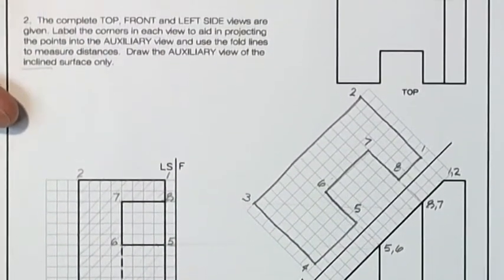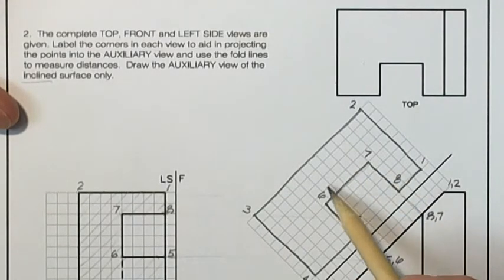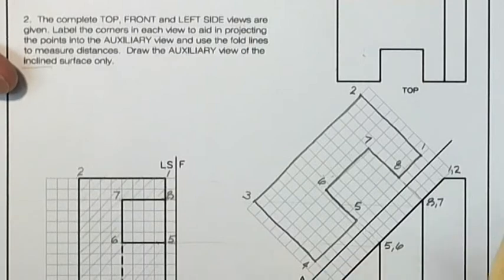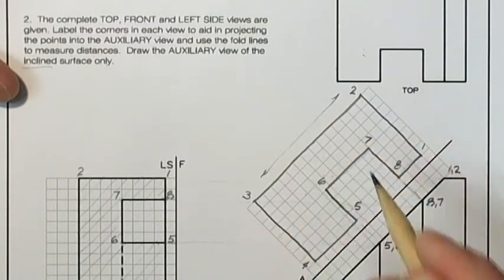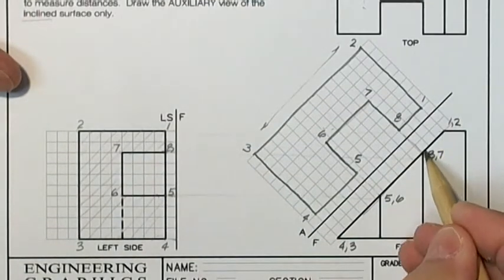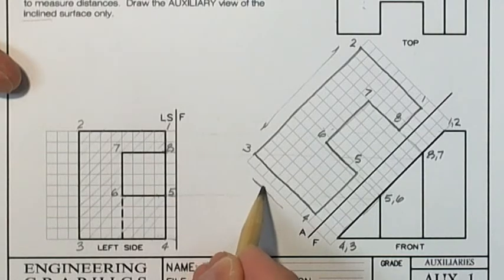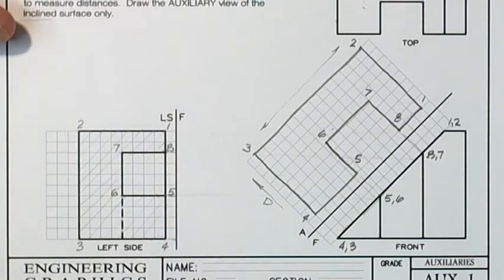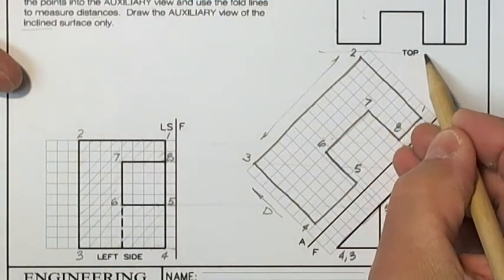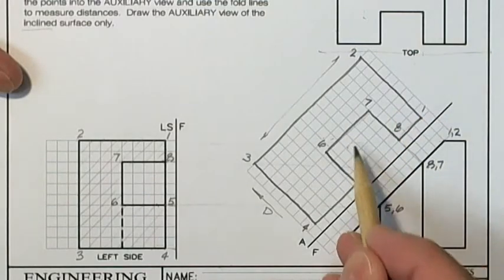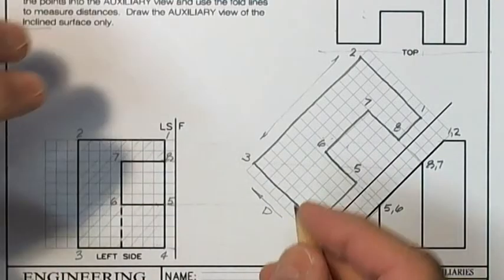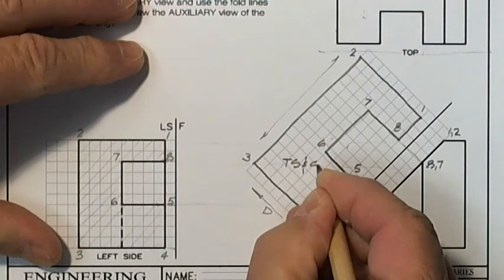Now, I'm going to slide this down just a little bit, and as you can see, this surface and this surface are really the same. It's just the shape from here to here that changes. And what I'm doing, I'm combining this true length measurement from here to here with, in this case, the depth. If I were to take this drawing, I could have had a fold line here in front of the top view and measured back, and still I would have the very same measurements to combine with the length of that inclined surface. And this, of course, is true size and shape.